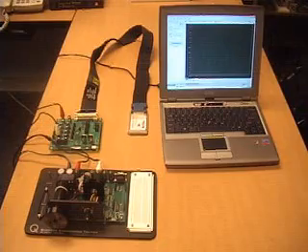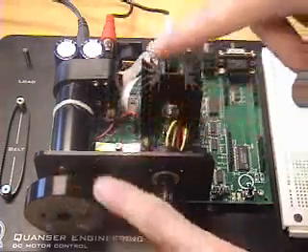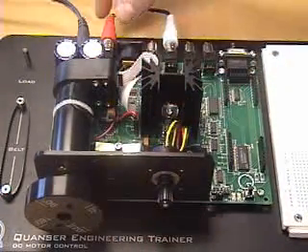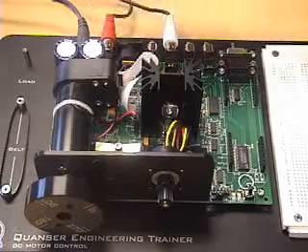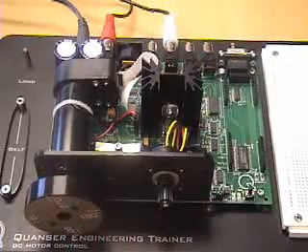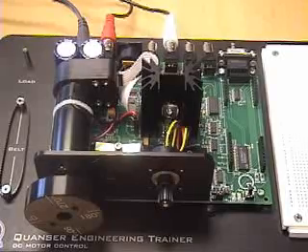The tachometer, as I spin the motor, essentially will output a voltage that's proportional to the speed of the shaft. And the input voltage that I have in, again, is coming through basically a power amplifier, and that controls the speed of the motor proportionally to the value of the voltage coming in.